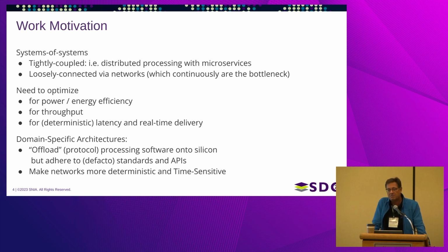Again, we make heavy use of FPGAs wherever we get them from these days. And we offload protocols and/or algorithms from software, typically open source software, into silicon. But unlike others who invent their own proprietary protocols, their own proprietary standards, we're a strong believer in open standards. IEEE Ethernet, IEEE TSN, which stands for time-sensitive networking, open source Linux. That's basically the standards and interfaces and APIs we adhere to, and which we are accelerating using offload engines.